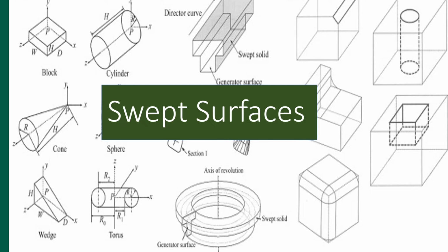Hi, this is Vijay. Today we are going to talk about swept surfaces. Swept surfaces are surfaces that are generated from a section curve positioned along a path. This path is generated by a trajectory curve. The main difference between skinned surfaces and swept surfaces is that skinned surfaces use many section curves, whereas swept surfaces use a trajectory curve as well as the section curve.